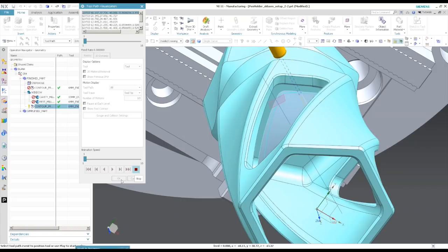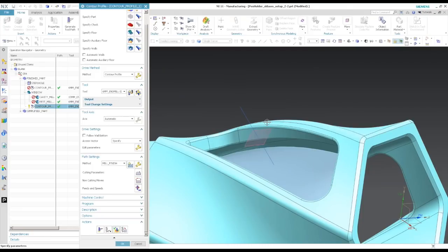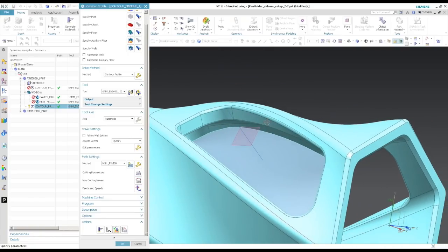There are certain cases, not so much with this one because the wall is not too deep, where the data was so bad that it was hard to even repair. The effort to try to get a swarf toolpath, for a one-off part, wasn't worth it, so we had to switch to a different method, and I would say 20x the toolpath time.